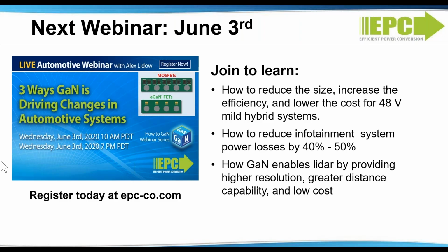Also, GaN really tests the skill of the engineer a bit more than a MOSFET. When you go to higher frequencies, you have to be more careful with your design and layout. You have to be cognizant of parasitics, particularly parasitic inductances.